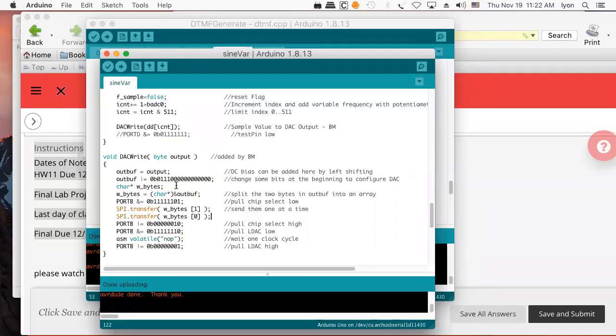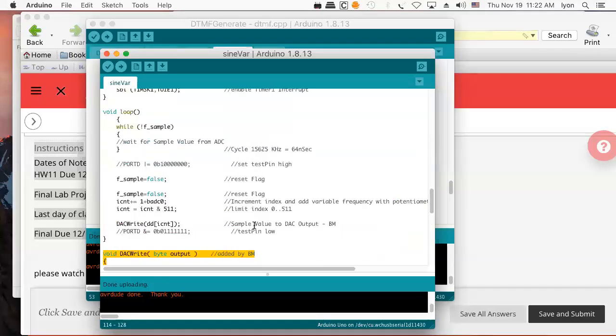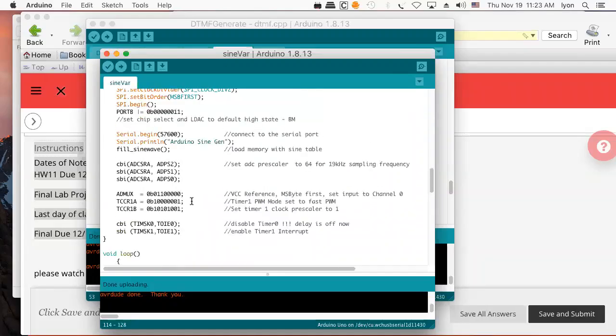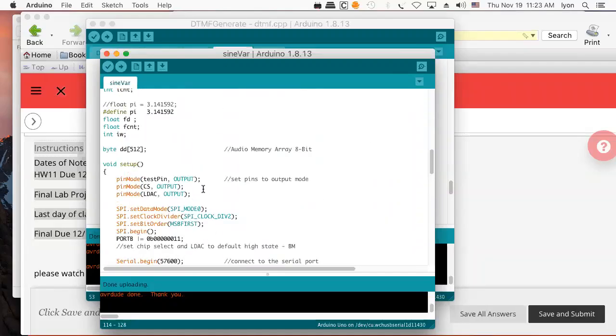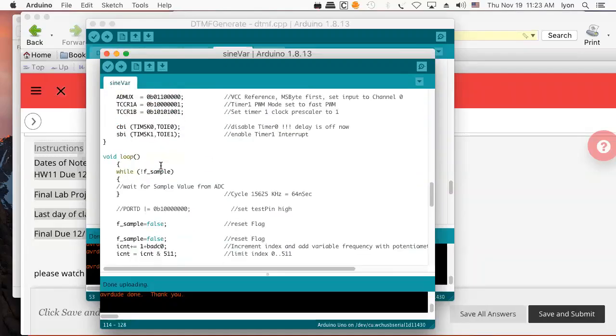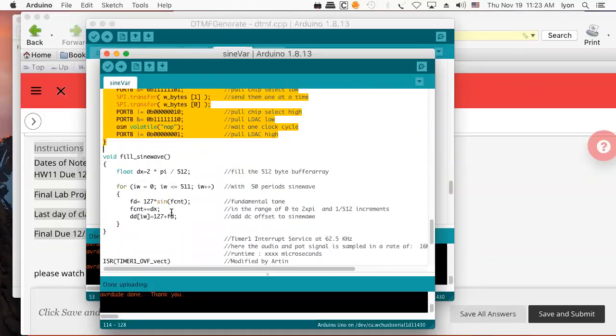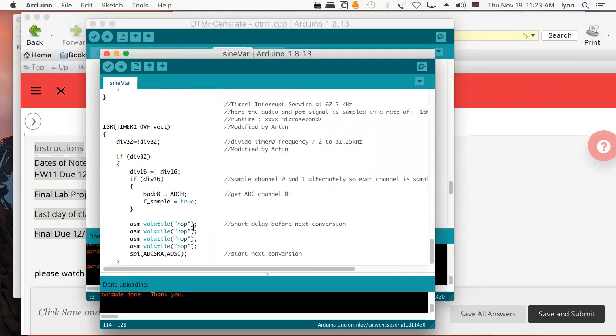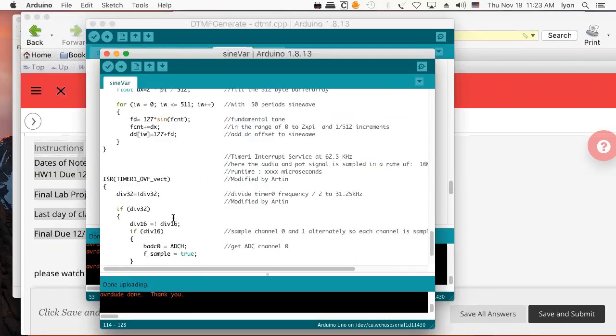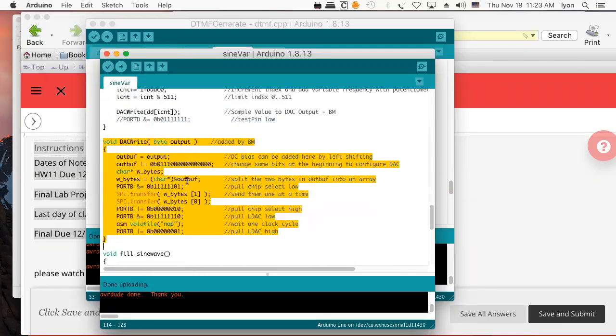And what we had in here was everything in one big main, which was a bunch of functions, a loop, a bunch of setup stuff, and kind of crummy software engineering, I thought. A way to fill up a sine wave, maybe a timer in the back that was running on interrupts to chug out samples to this little SPI DAC, and that was for the MCP4921 DAC.